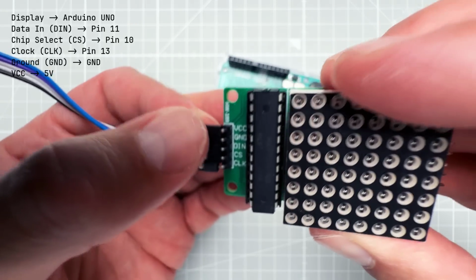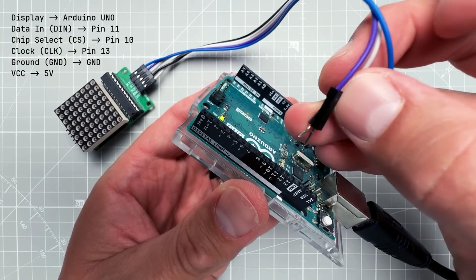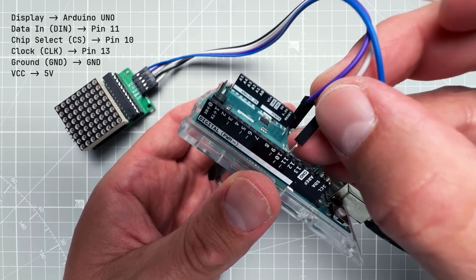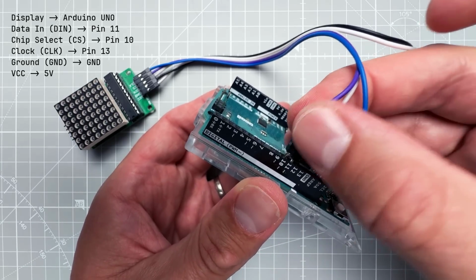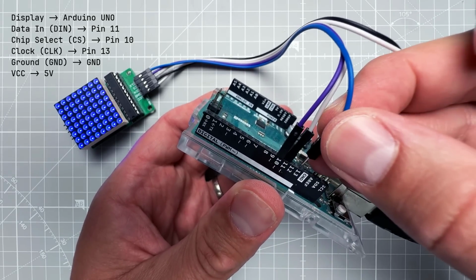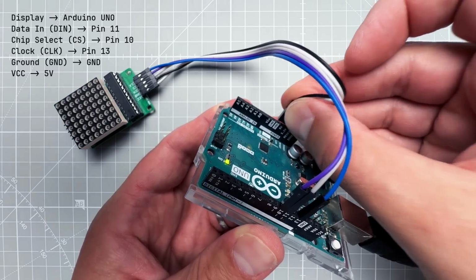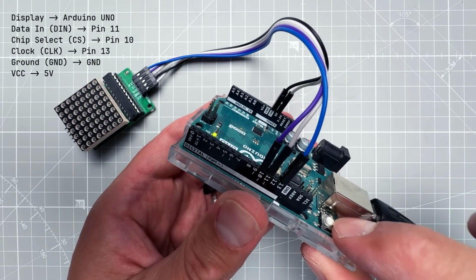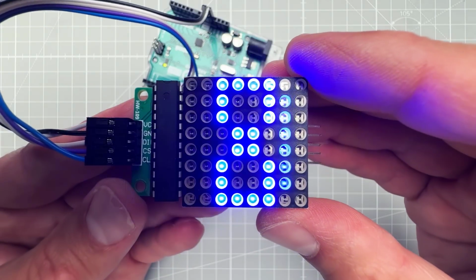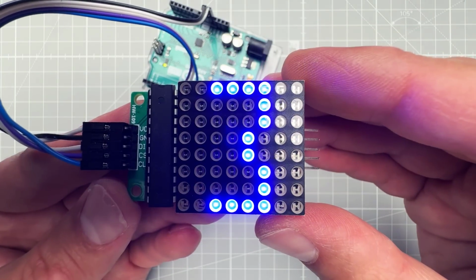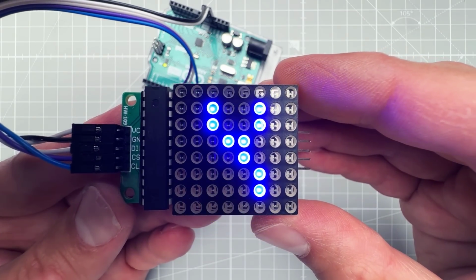To connect the Arduino UNO to the display, we should use the very same connection as inside the Wokwi sketch. The DIN pin, the data in pin, should be connected to pin number 11, the CS pin, the chip select pin, should be connected to pin number 10, the CLK pin, the clock pin, should be connected to pin number 13, and then the ground should be connected to ground and the VCC to 5 volts on the Arduino board. And once we have it connected like that, we should see those individual digits lighting up on the LED display. And even now, those look like proper numbers, proper digits, but I'm sure they will look even better with the 3D printed overlay.